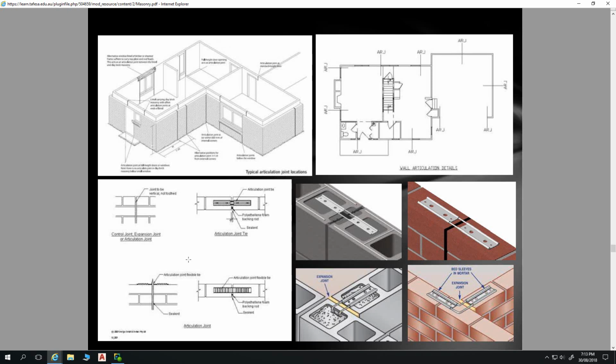So simply what building designers do is they look at the limitations around a brick control joint, and they specify everything as a BCJ around the building. So a brick control joint, the limitations on that are the sum of the requirements for an articulation joint and an expansion and contraction joint. Does that make sense? But basically the short of it is we specify brick control joints.